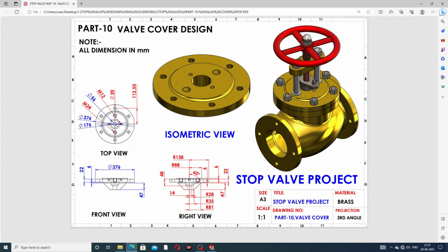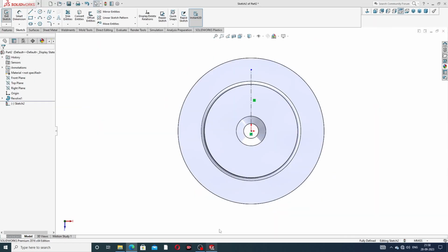And select this, a pattern, and this diameter is 20 millimeter, and this distance is 112.5 millimeter, and the pattern is 6 pattern. Okay, and this distance is not mentioned here, but this distance is 120 millimeter. This is perfect and correct. This distance is mentioned here, but apply a thread, and then the distance is 120.